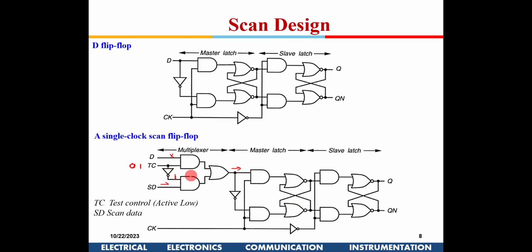These are the kind of flip-flops which we are going to use now. In most modern processors, the flip-flops will be like this. This is one design where the mux has been incorporated here. One disadvantage will be the delay for the D. The total delay and setup time will be slightly worse here, because one mux has come in between.